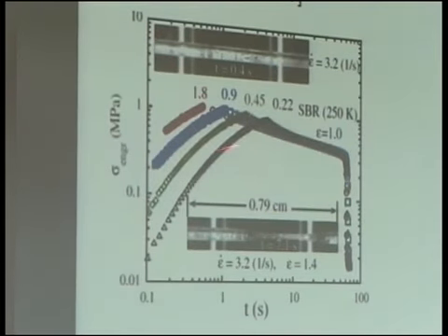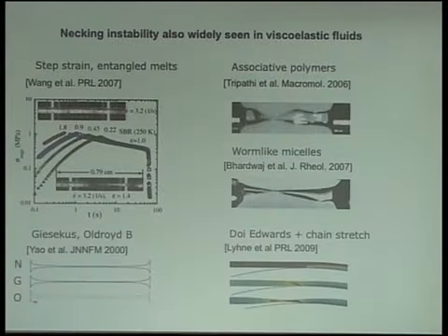So this is real experimental data, this is simulation data. This is from Rasmussen's group and Hassager. What they're looking at here is stretching a filament between counter-rotating cylinders, and this is a simulation focusing on the regime where the sheet, it's actually a sheet here, not a cylinder, contacts one of the cylinders and it fails there. This is a simulation from Gareth McKinley's group using either a Newtonian fluid or two different complex fluid models, Oldroyd-B or Giesekus, and he sees something that looks like necking here as well.